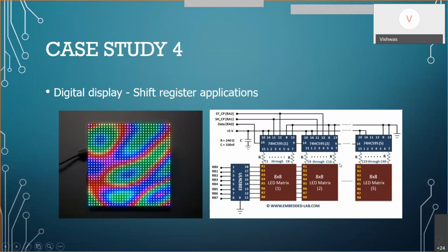So the basic idea is, using shift registers, you will be able to control the whole bigger display. With the help of shift registers only, you can realize a matrix display of however big a size you want, and it is hot swappable. You can directly remove one of them and put back another. If you have a smaller screen, you can increase the screen size. All those things can be done. You just need to ensure that all the data is sent on the right edge of the clock. That is the basic idea behind large matrix displays.